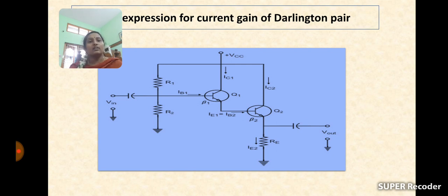So this is about the need of resistors R1 and R2. What is the need of resistors R1 and R2? It provides the biasing and stabilization. What is the need of biasing? To make the operating point independent of temperature variations and transistor parameters. If R1 and R2 are not there, the leakage currents will increase due to temperature variations. Once the leakage currents increase, the Darlington pair circuit will automatically provide low gain, due to the disturbances produced. So this is the use of resistors R1 and R2.